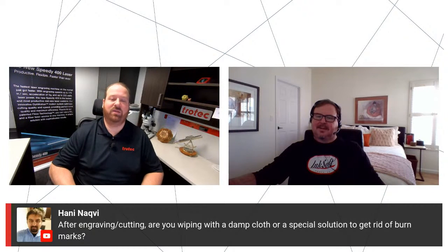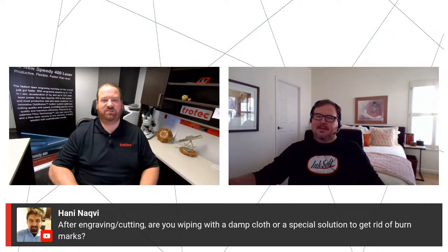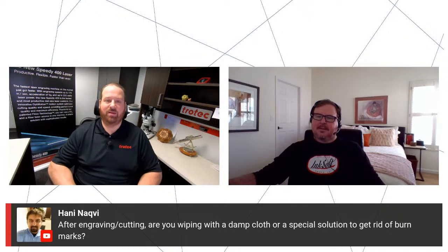For example, do not use alcohol after you've engraved acrylic, because it'll crack the acrylic. So you want to use something like the LA Awesome cleaner, which works really well, or any other cleaner more suited to the material if it's got a stubborn type of staining. But in most cases, I just use a semi-damp cloth to wipe the surface after I've done cutting and engraving.